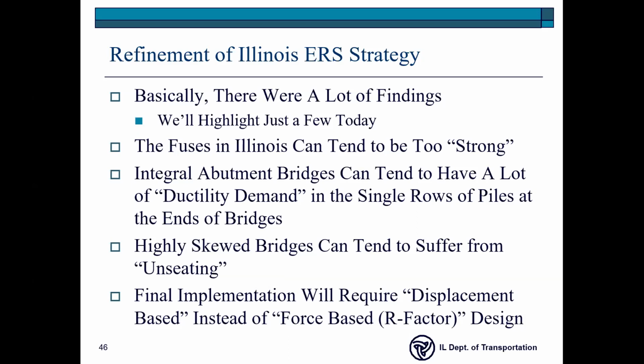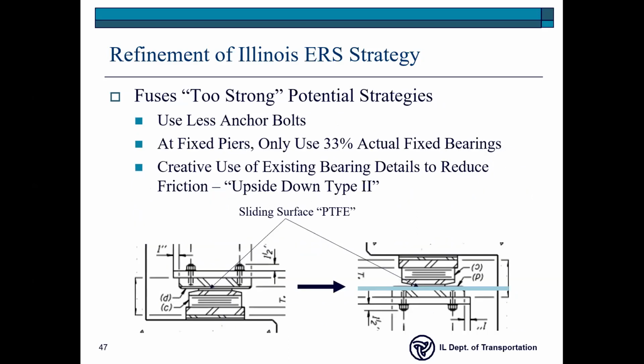And another thing we found out is that in order to really implement a good design calculation strategy to fully utilize our quasi-isolation, we actually have to go from R factor or force-based design to displacement-based. So that's really going to be a big deal for us over the next couple of years, when we actually teach structural engineers to do that across the state.